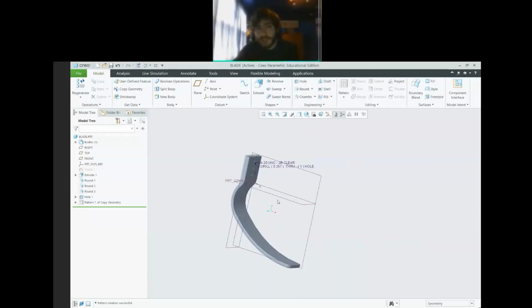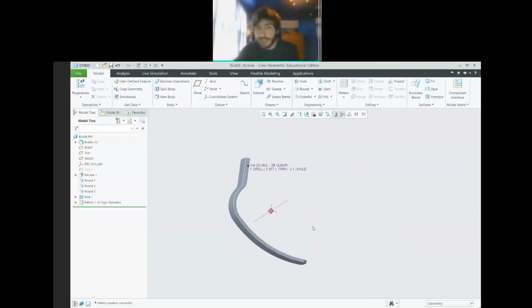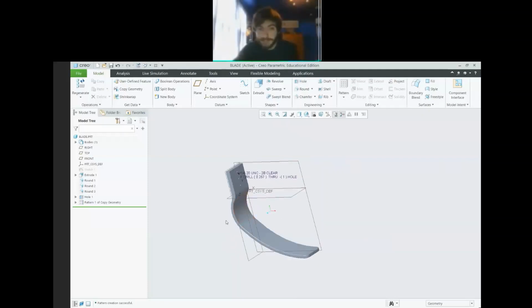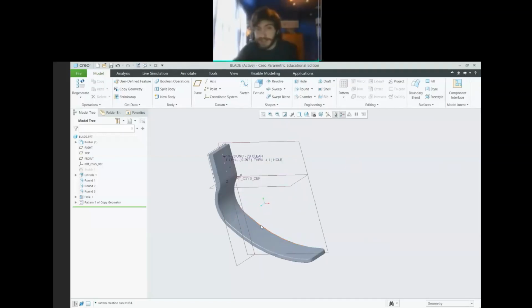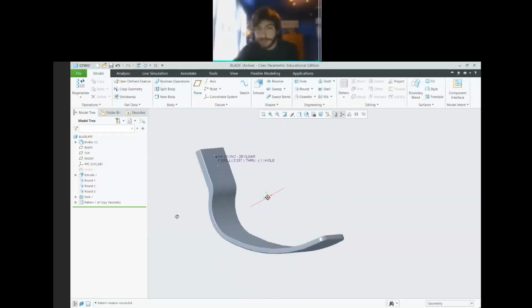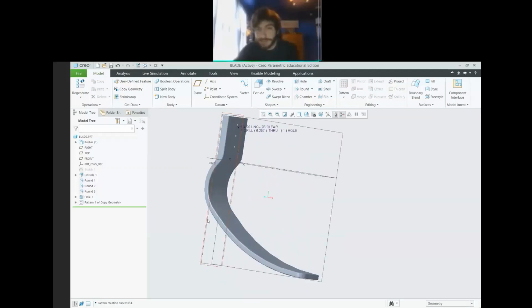You could also do it by making a sketch that's the same thing we did, extruding it left and right as a surface, and then thickening the surface. Yeah. But this is, I think, probably the easiest and most straightforward way to go about it.